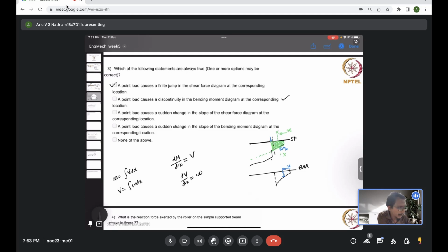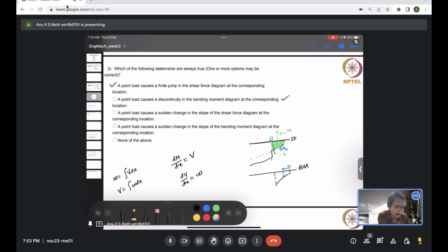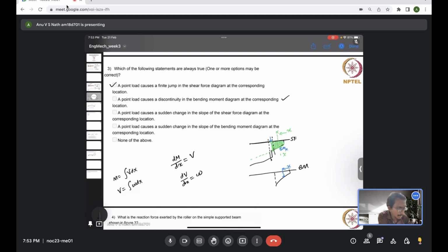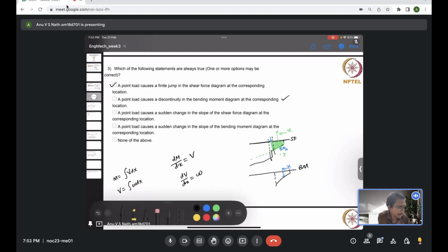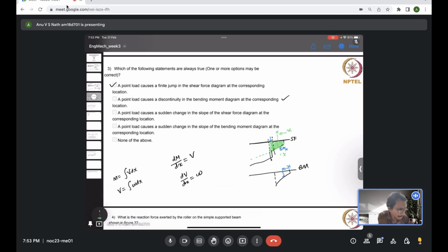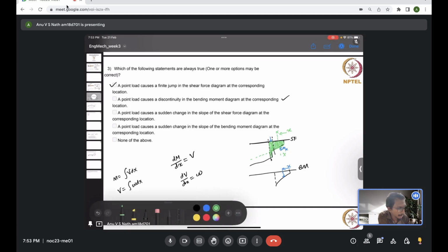Now just the area, if you evaluate, it will be like a quadratic profile as I have drawn here. Now if we consider a point which is limitingly after, in the limiting sense, after the point load, somewhere here, I mean it should be very close to that particular location where the load is actually acting. And now if we ask what is the bending moment, we have to basically evaluate this area, marked in green color.